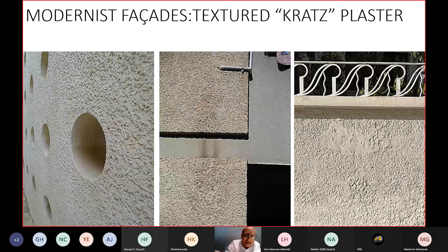finishing. But because it was troweled very strongly with this, it's a very hard material, very long lasting, and totally adhering to the surface of the cement blocks or the concrete. And this also, to be cleaned, is cleaned with a Karcher applied at low pressure. And because it's also tinted within the mass, this plaster is very hard and very long lasting and doesn't need to be painted.